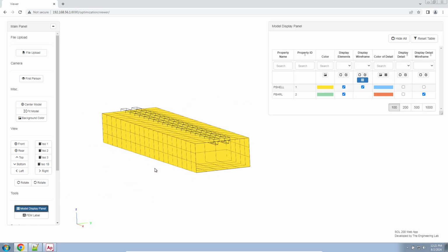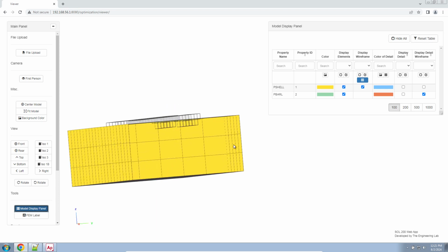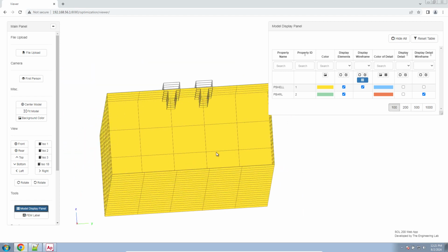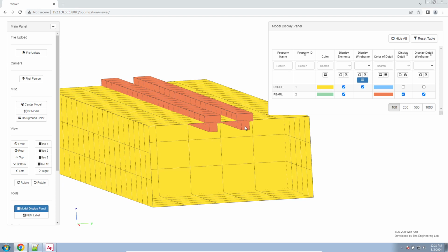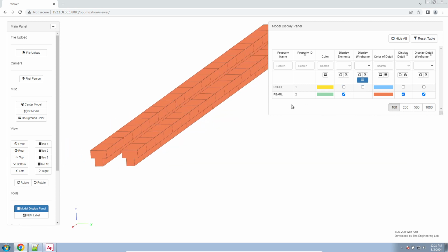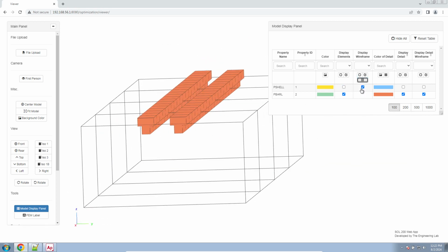Here we have maybe the skin on the exterior. Here in the middle, we can consider that the rib of the wing. Here are these beams or stiffeners. These can represent the stringers in the wing. And then one thing I don't have in this model, I don't have a spar. So maybe during this exercise, we'll go ahead and add our spar in the interior of this wing.